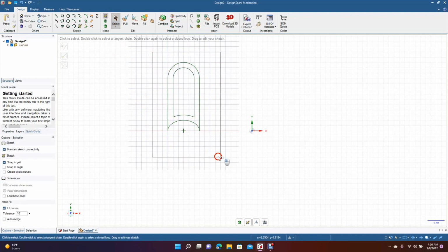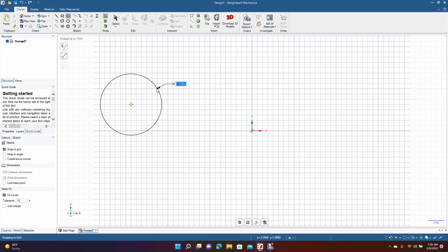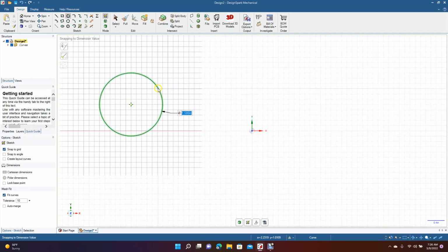Okay, so that's a good use for those, for your three-point arch, your ellipse tool. I use my three-point arch a lot, but it's probably best to use it if you're just going from endpoint to endpoint and you're not going from an actual arch, because it's just pretty easy to misalign things when you're using that.